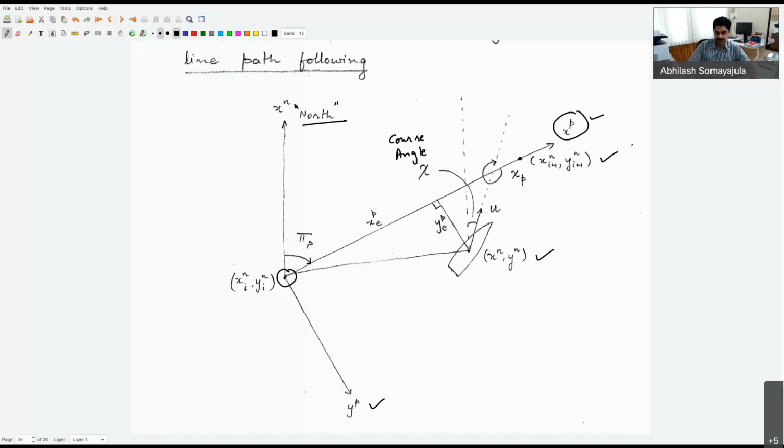Okay, is everybody seeing this? Same idea, only that the path tangential system's x-axis is pointed in a different direction. Notice that in both of these cases, the positive convention will always be governed by the right hand thumb rule with the thumb pointing in the z direction. Since z is pointing down, the clockwise direction is taken as the positive direction. Is everybody with me so far? Yes, sir. Okay. All right.